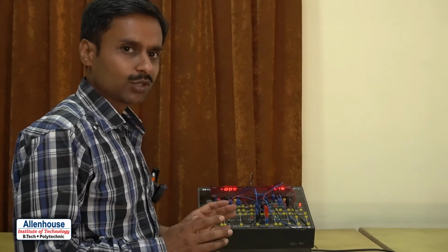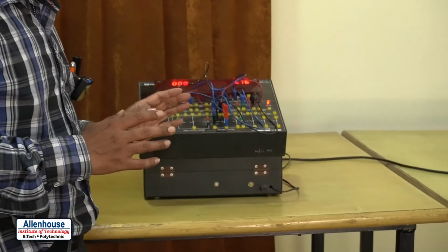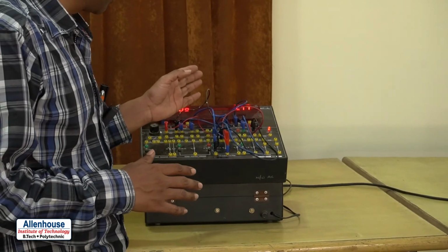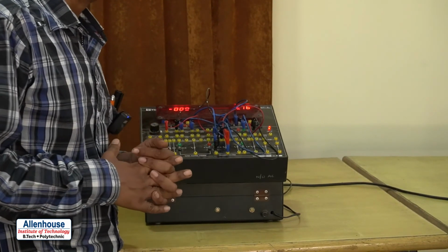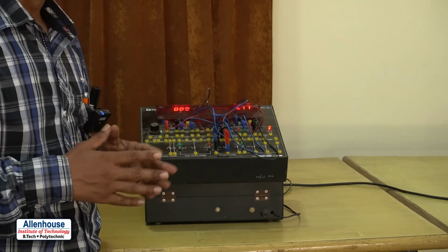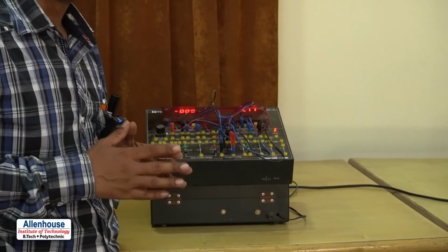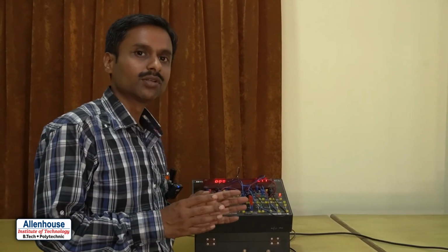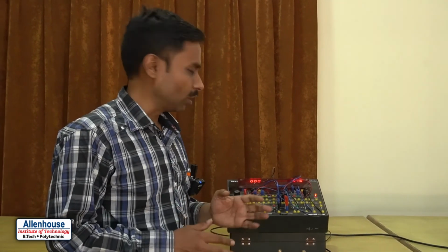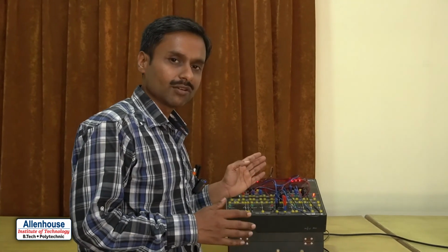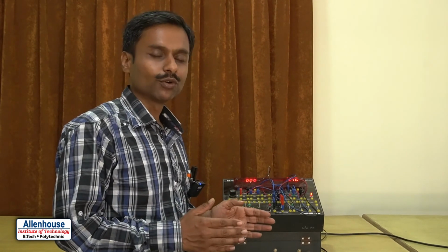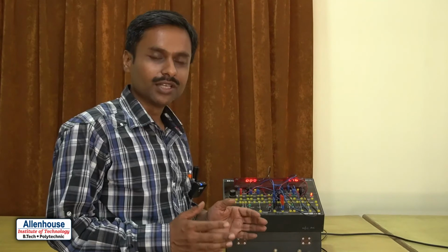There is a little fluctuation in the voltage, so the reading fluctuates a little, and it comes out to be 5.77 or 5.78. So it is nearly approximately 6. We can say that we have verified Thevenin's theorem, because there is a little chance of error due to voltage fluctuation. The reading is 5.78, which is approximately near 6 volt. So V_Th is 5.78 volt, and we have verified Thevenin's theorem.